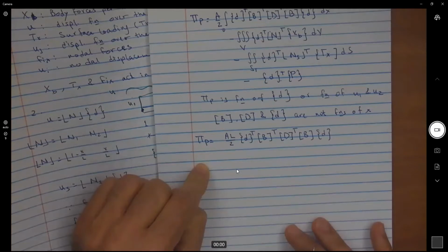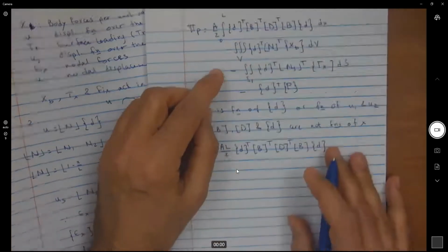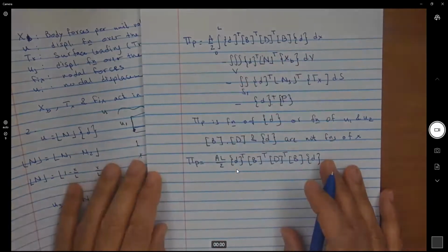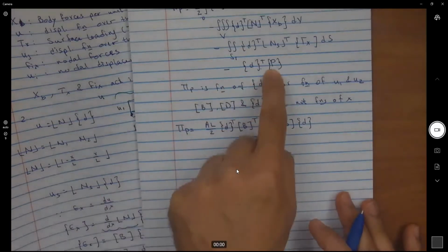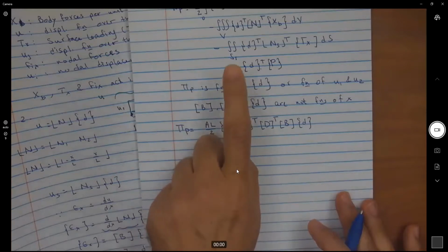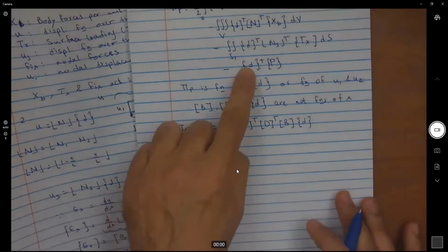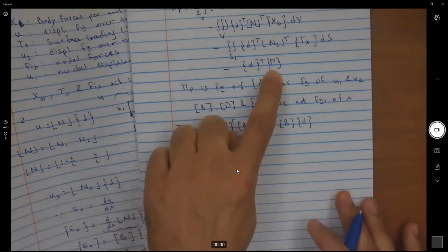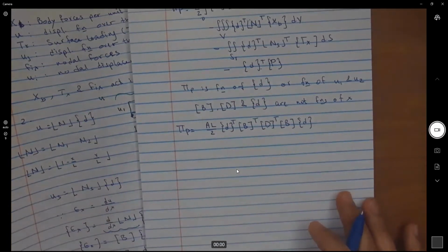Consider these forces may not be there. If they are not, doesn't mean the equation reduces down to that? Correct. So if I don't have xb, for example, if xb is a 0, so this term is going to be gone, right? But we're trying to derive it for a general case. So actually, typically, since you mentioned that, Tarzan, typically, these are the ones we're dealing with. But we're also using this opportunity to evaluate equivalent nodal forces should I have a distributed load along the element. Okay? But the most common would be this, the nodal forces, P. Okay? Or at least we want to convert all the distributed load to nodal forces in order for us to be able to apply to the element.